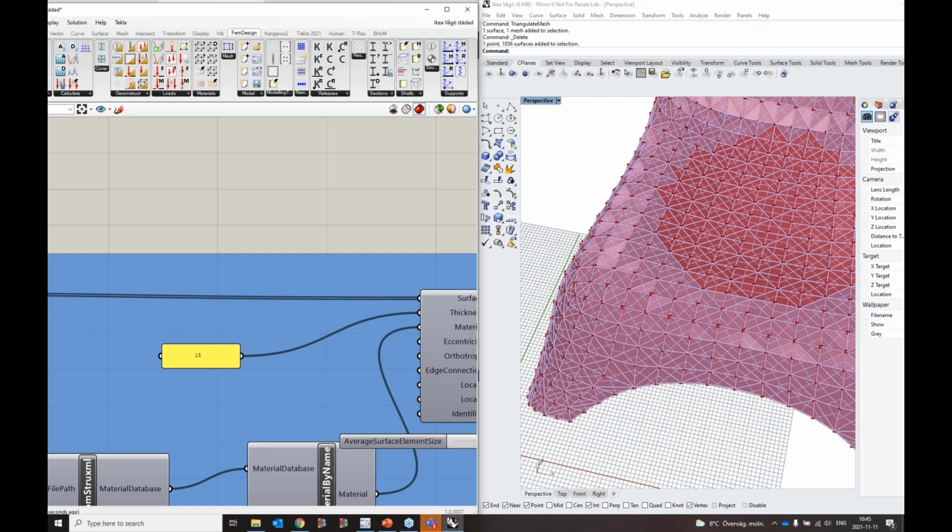But basically, what you do is you have a C# project that you use to open FEM-Design, generate geometry, send different commands to FEM-Design on what it should do, export different results and so on. So you're running FEM-Design through the C# application regularly, or that's what I have done. But you could set it up in different ways.